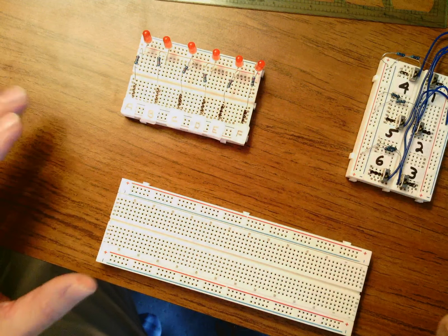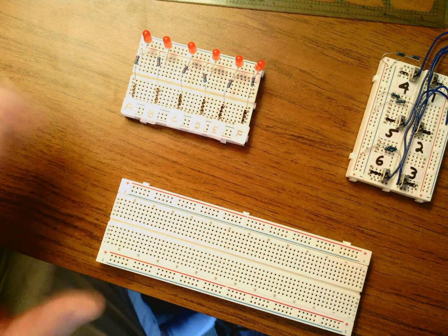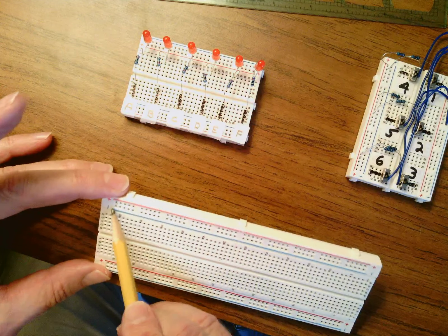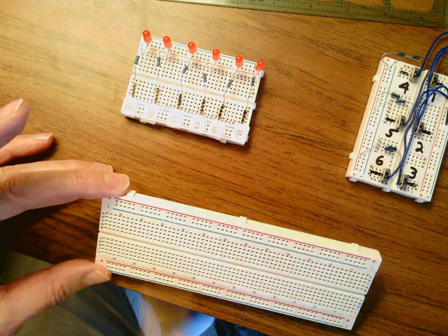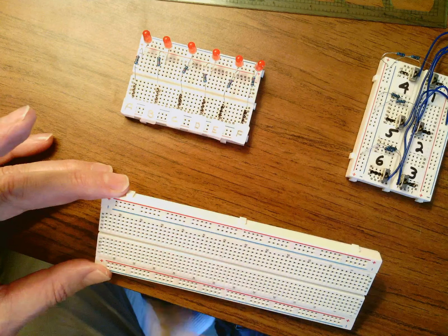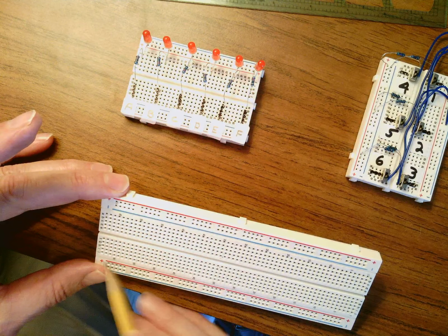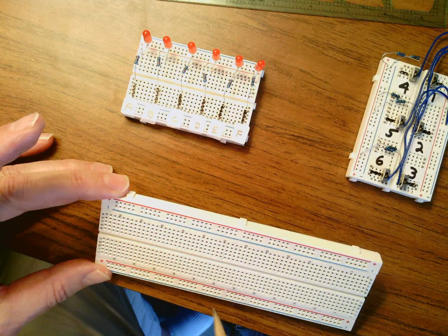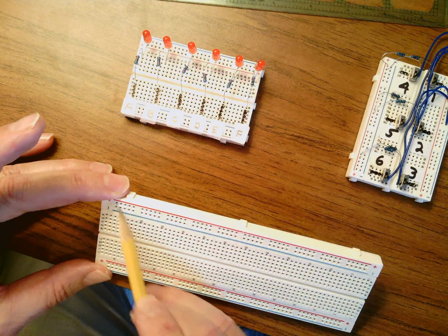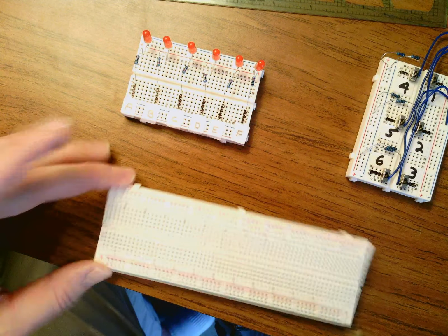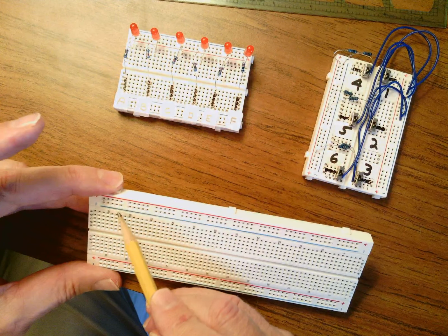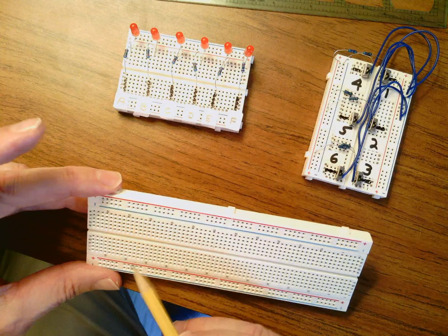Now, I have some handouts that I'll be providing to explain all this, but in this lab, I want to make it really clear to you that you're never going to use the top blue rail in any of these boards, and you're never going to use the inside red rail. The only rails you will use on these boards are the outside red rail and the outside blue rail. Here, the outside blue and the outside red at the bottom. On your switch assembly, the outside red and the outside blue. The reason is because I don't want you to short things out. These are too close together. So you'll never use the inside blue and inside red on any of these boards.